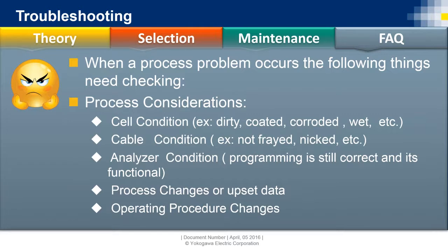If you get a brand new sensor, you stick it online, and you've put in that cell constant. Remember, with contacting conductivity, you have to put in a cell constant, a multiplication factor: 0.1, 0.01, 1.0, 10.0. If it's off by a factor of 10, it's a good indication that there's something wrong with how I programmed my cell constant. And it could be as simple as the analyzers normally auto change from micro to milli Siemens. If we put in a cell constant wrong, it could be that, and that's most commonly what we see, and most of the time the problems are just at startup.